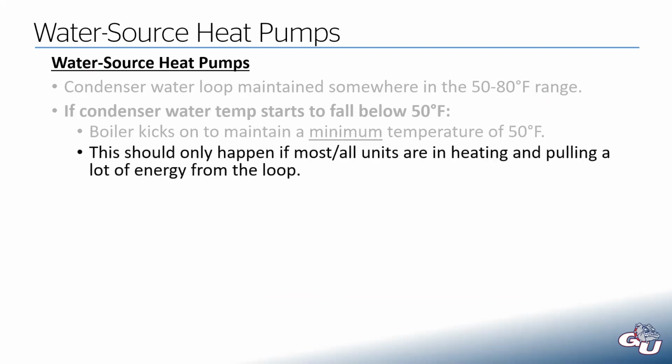But this should only happen if most or all of our heat pumps are in heating mode and they're all pulling heat out of the water. If all of your heat pumps are in heating, they are extracting a lot of heat out of the water to then deliver into your space. And that means your water temperature will start to drop.